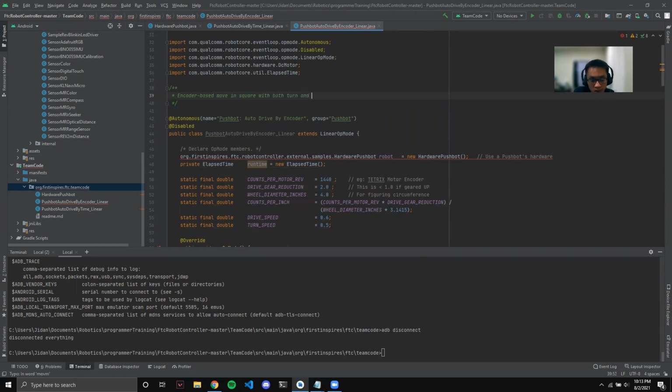So the idea is, one of the methods will be going forward and turning, but also turning. It's kind of tough with encoders, because encoders are pretty good for forward direction movement and left-right movement, but when you're turning, that means you're rotating. You've got some funky geometry you might have to work with, and so generally that's when we look at gyro. But we'll still create a turn one with encoder, just as part of the learning process.